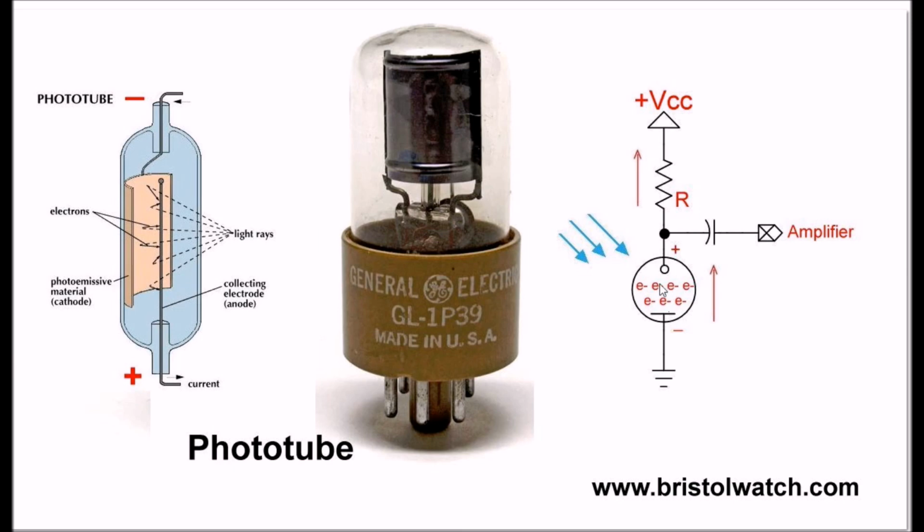And depending on the intensity of the light shining through the film onto this phototube, you have your audio signal, which passes through a blocking capacitor and is sent to an amplifier. So that's how your old reel-to-reel films had audio. Your earliest ones did not. It wasn't until they developed vacuum tube amplifiers, probably after the 1920s, did you really start to get audio on your films.